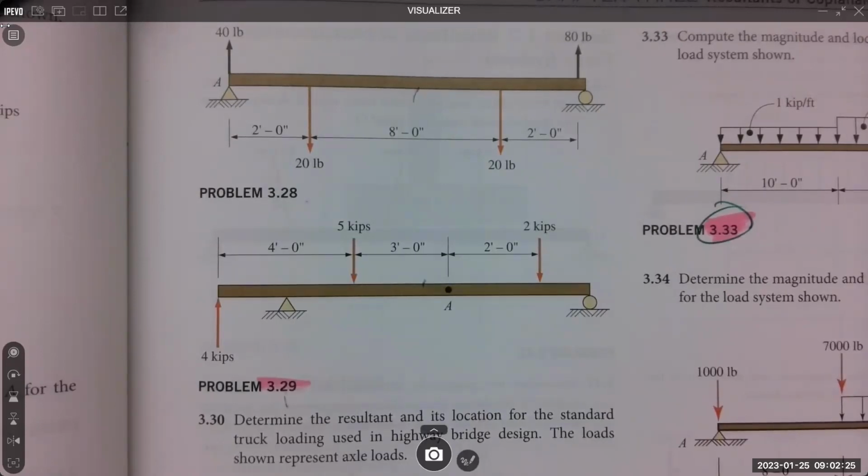For the chapter 4 question, is there a difference between the structural integrity of the shapes? Yep, absolutely. The triangle is a knife edge or a pin. We use the triangle for both of those. Most of the time it's a free pin, meaning free to rotate, right? And the roller can only hold in the Y direction. It can't hold in the X. Thermal expansion: we put thermal expansion joints in everything and connections. So if it heats up, it can expand. If it cools down, it can roll.